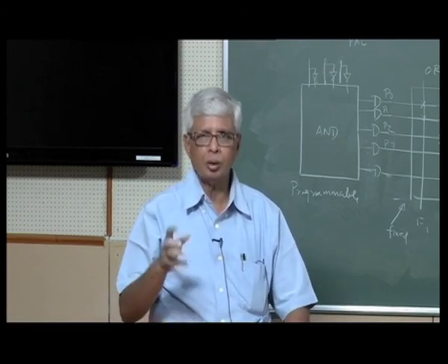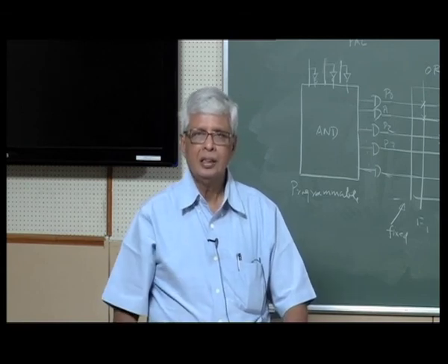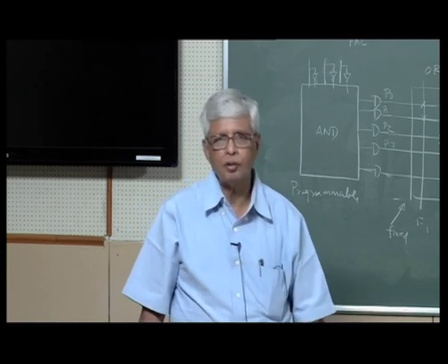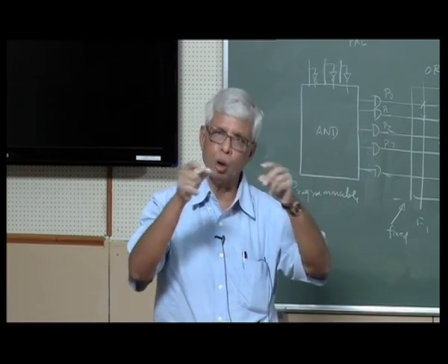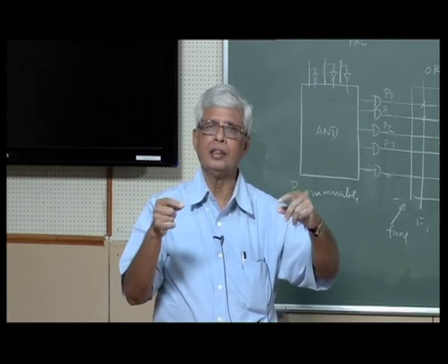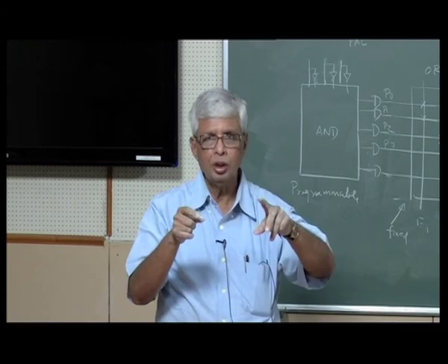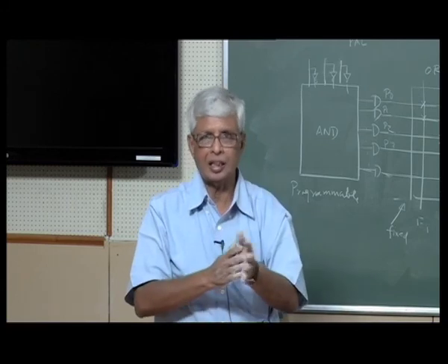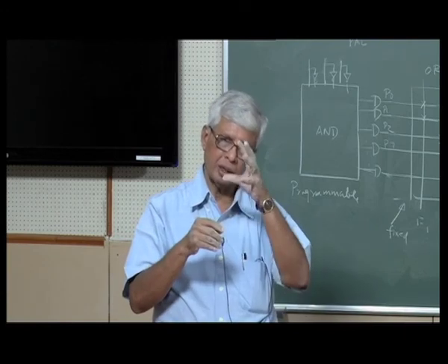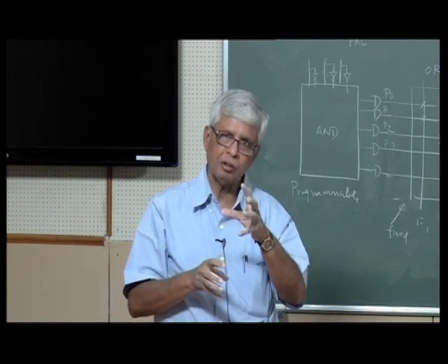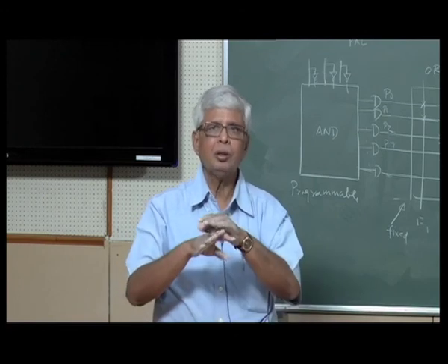That is what I said, it is storage in the sense, it is a memory in the sense, whatever you put remains. It does not disappear when you switch off the power. Because of the technology, as I said, there are fuses. The fuses can be blown: if you want a connection, retain the fuse; if you do not want the connection, remove the fuse. That is the earliest technology, mask programmable. Or today you can do it electrically, a charge can be changed. For one type of charge you have a connection, for the other type of charge you do not. So all these are done, but there is no going back on it.